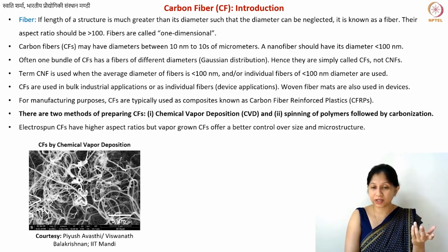This is also a process which we will discuss for carbon nanotube fabrication, because tubes and fibers both can be fabricated using this method. Fibers are basically not hollow. Tube is hollow, fiber is not hollow. There is a certain critical size of your catalyst, after which you will rather get fibers than tubes.